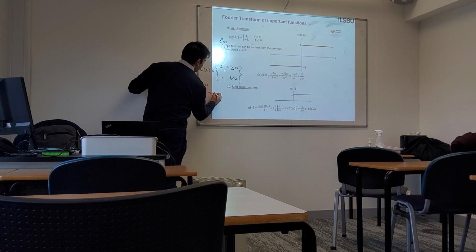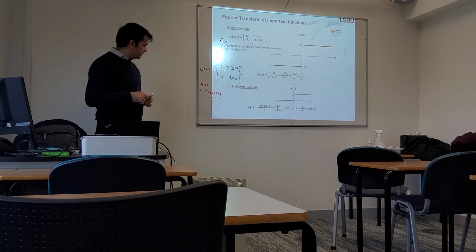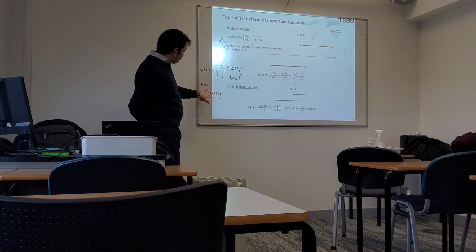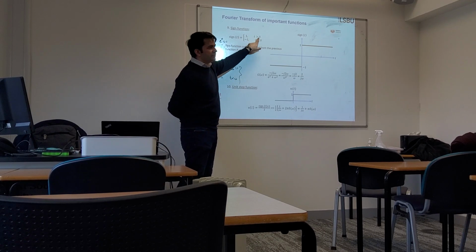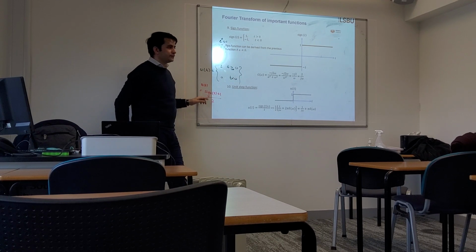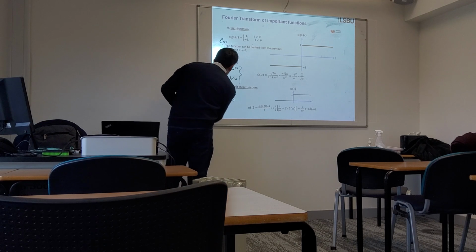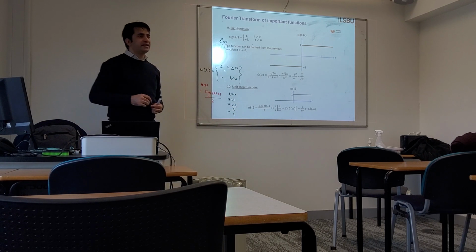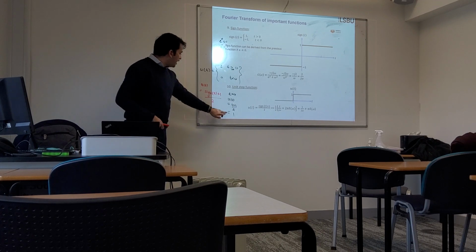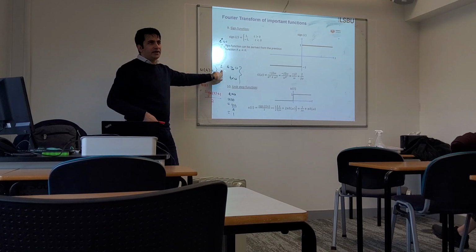Now, if I come to this equation, I have equated the unit step with the sign function of t plus 1, divided by 2. How will this work? See, if t is greater than 0, the sign function is 1, right? So for t greater than 0, u of t is (1 plus 1) by 2, which is 1. So for t greater than 0, I got the same value I was expecting.